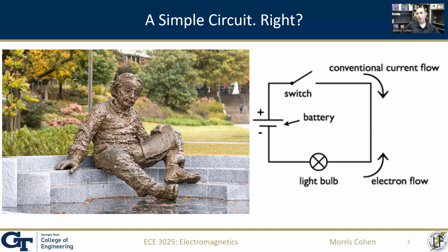And that's primarily why we have to consider this not as a single circuit that's instantaneously small, but as a transmission line. There will be a back and forth process of the battery sort of finding out what is at the load and establishing that proper current that we know will be the case from basic circuit theory.